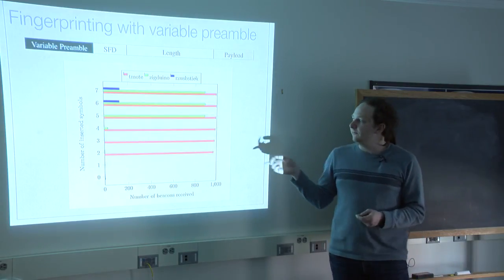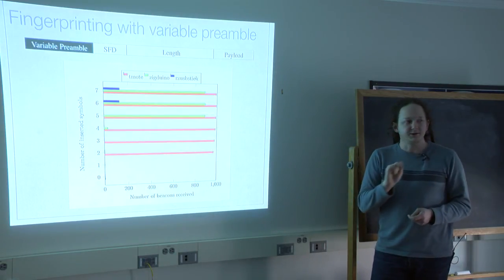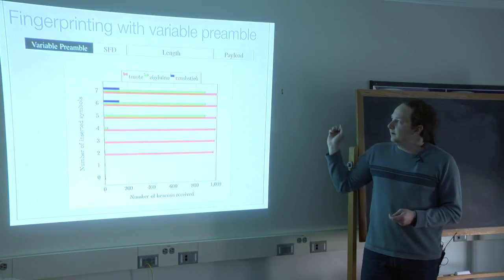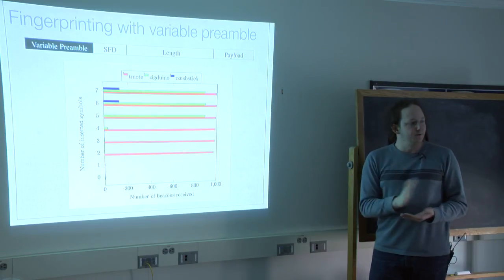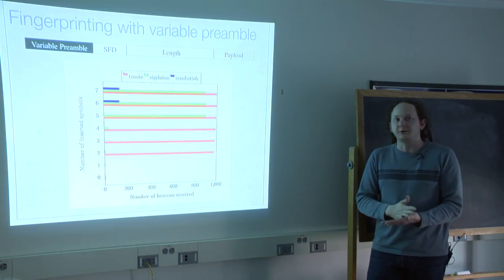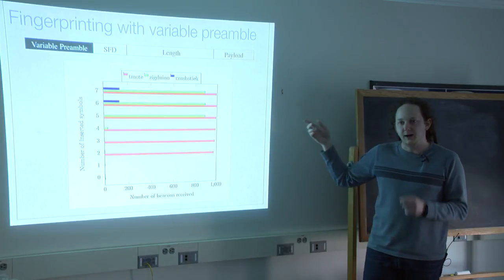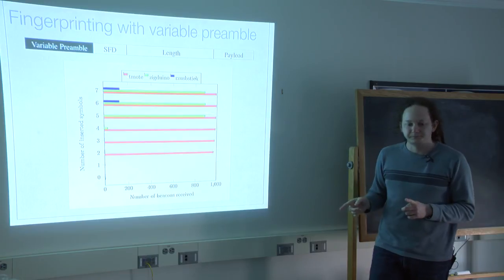The ChipCon 2420 does this the most often because it's matching on the shortest sequence. It matches on just 4 nibbles, 00A7. The RZ USB stick, even with checksumming disabled, shows very few because it's matching on almost the complete preamble as part of the start of frame delimiter.